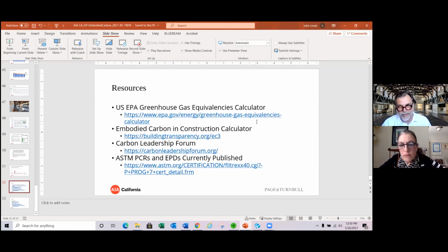So we find that when we do wood repairs and look 20 years out, we didn't necessarily replace redwood with redwood. It's the new stuff that is getting eaten by the termites or having mold and mildew issues. So there are other benefits. I'm a big proponent of saving and reusing old growth redwood and Doug fir and that sort of thing.